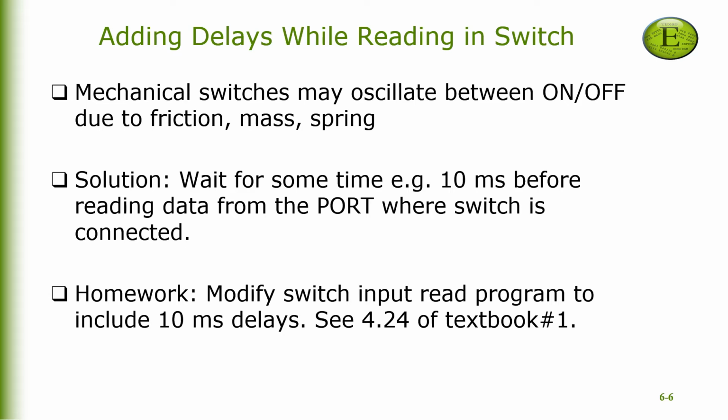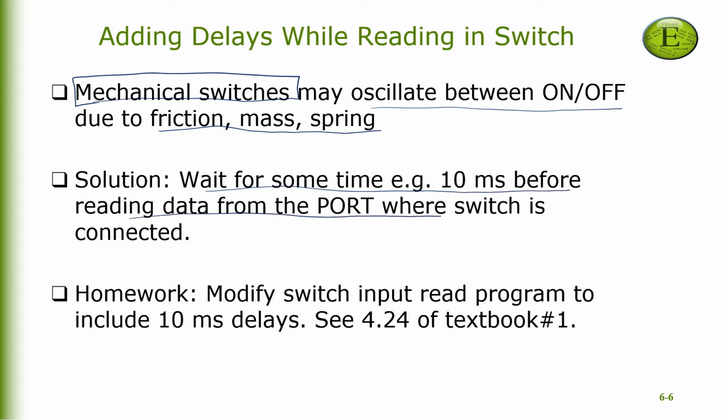Next, whenever we are interfacing mechanical switches with the microcontroller, we should always remember that mechanical switches may oscillate between on and off state due to their inertia, friction, mass, spring, and other mechanical properties. In that case, it is better if we wait for some time, typically up to 10 milliseconds, before reading the data from the port where the switch is interfaced.